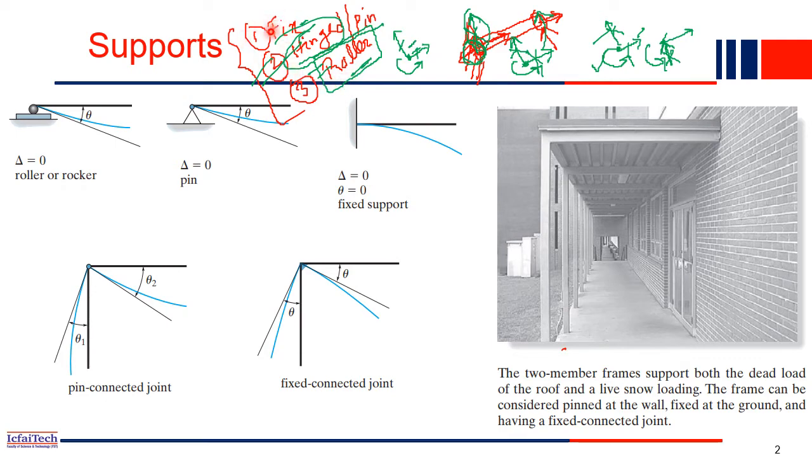So it is very important that you understand we have three supports. One is the fixed support. If you see the beam column joint in a structure, wherever you are sitting, that beam column joint is basically a fixed joint. Similarly, hinge joint means the door is connected through a hinge to the wall, right? We call it a hinge joint or pin joint, both are the same. And then lastly we have the roller joint or roller support. Basically, in a sliding door or sliding window you will find the roller support. Okay, so these are the three supports.